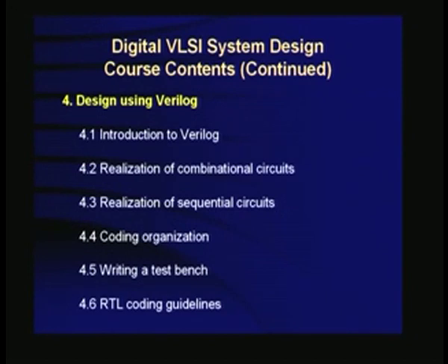So once you do Verilog, we'll again introduce you to Verilog properly and how to realize combinational circuits, how to realize sequential circuits, and how to code it. Realizing is just simply writing, but then you have to organize the code properly for efficient design. And you have to test it. Writing a test bench is important. How do you know if a design is going to work? You cannot fabricate it every time. So you have to write what is known as a test bench. And when it works with the test bench, it will work with your design finally.